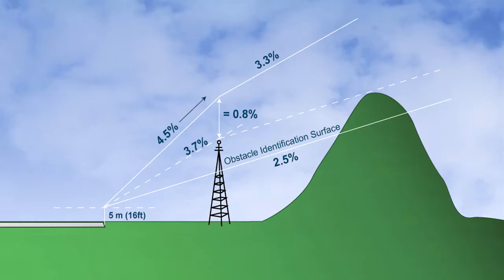Alternatively, the aerodrome operating minima could be increased until the obstacle can be avoided visually. In the turn initiation area, the minimum obstacle clearance of 295 foot is provided. Of course, in specific areas of more mountainous terrain, increased obstacle clearance will be afforded. If DME is available, additional height or distance information is made available. Mountainous terrain is not defined, but when designing departure procedures, if average wind speeds of more than 20 knots prevail and the terrain produces downdrafts, then increased obstacle clearance criteria are applied.